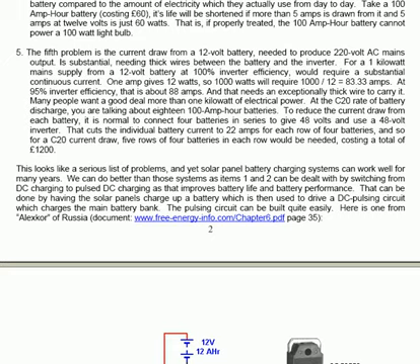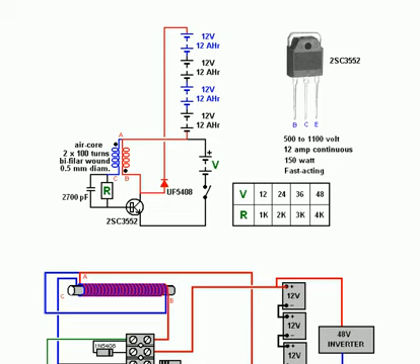one transistor. In this case, the transistor is a 2SC3552 transistor, which has a massive specification. It can handle anything from 500 to 1100 volts. It can pass 12 amps continuously. It can dissipate 150 watts, and it's very fast acting. As to the power dissipation, you'll notice there's a metal plate as part of the transistor. That metal plate needs to be clamped to a heatsink if you're going to run large currents through this transistor continuously.